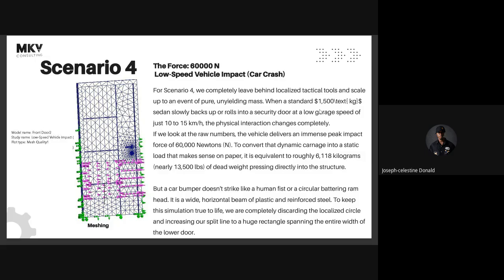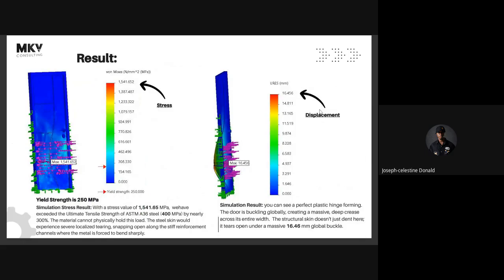All right, so you run your mesh, you do the same thing, and then you get your result. Now, even at default deformation, you can see how much it changes. You can see how much deformation comes out from it. It is steel that actually works at 250 megapascal, now against a stress of 1540. So you see a huge change right there. Okay, so you can see it deforming, and then when you look at the deformation with 60 millimeters, you understand.